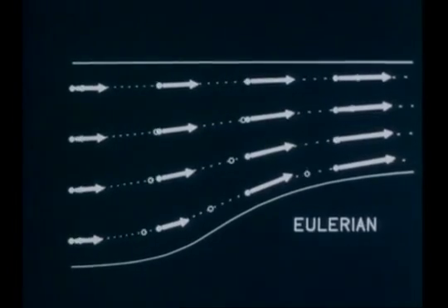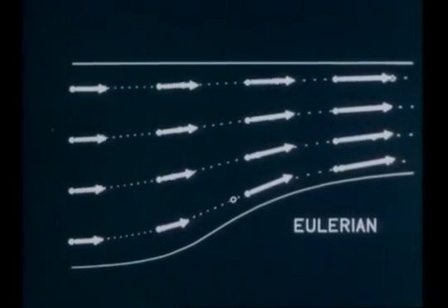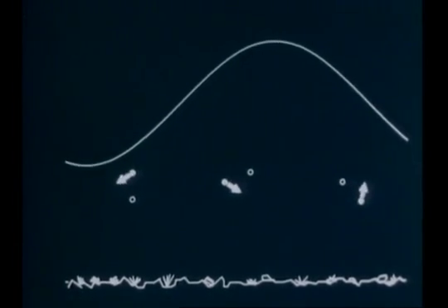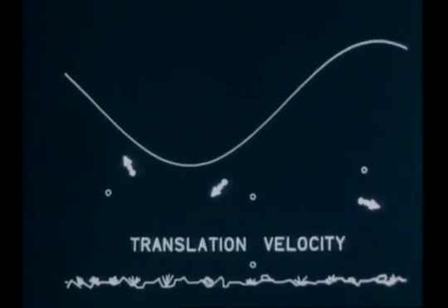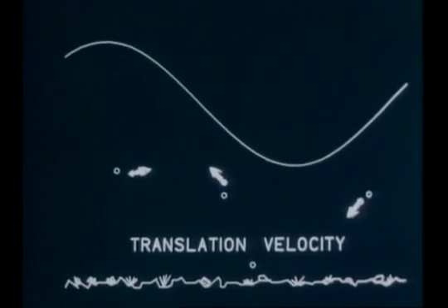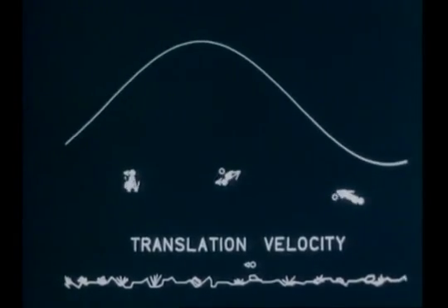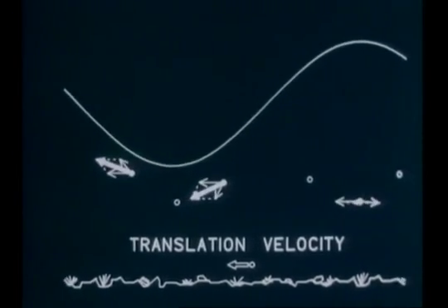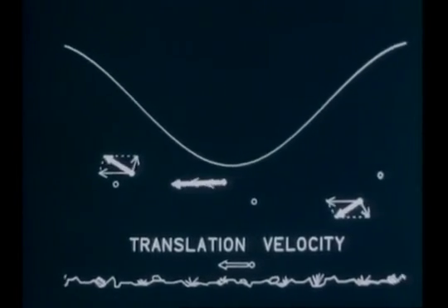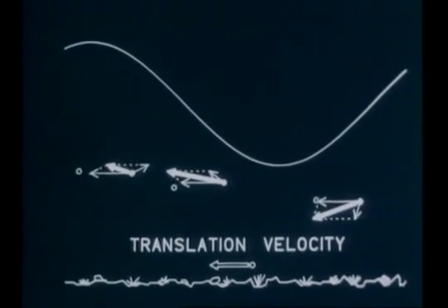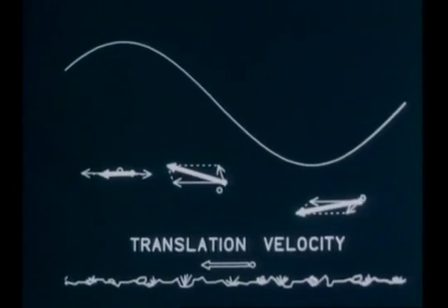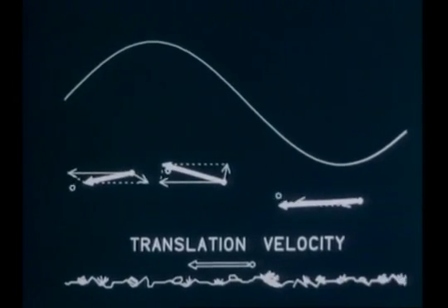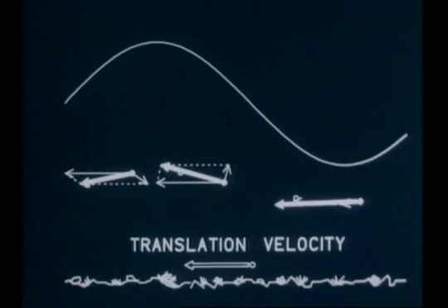This is called an Eulerian description. This has the advantage that it is sometimes possible to find a system in which the flow is steady. It is also mathematically enormously more convenient. We nearly always write the conservation equations for a continuum in this Eulerian system. It has the disadvantage that we're not always referring to the same material point.